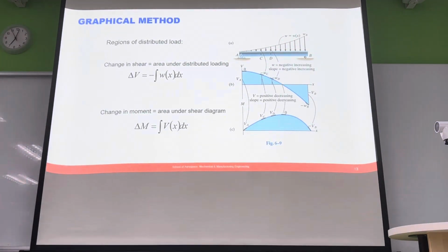Another way of saying that is that the value of the shear force at any point x is the gradient of the moment. So here, the value of the shear force is 0, therefore the gradient is 0. Here the shear force is at its maximum positive value, and that means this gradient, the slope, is that value, and that's the most positive gradient of M we will have.